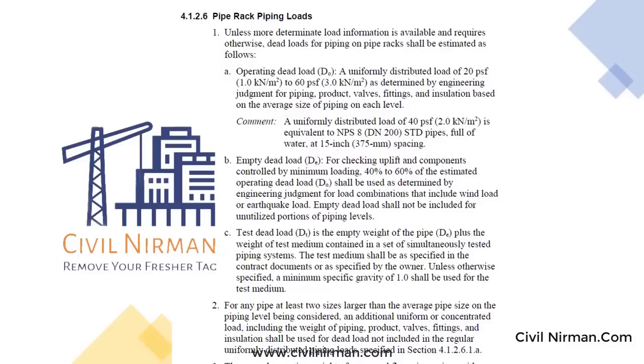Test medium shall be specified in the contract document. When such data is not available, water-filled pipe weight is considered for the test load. Hence, for big bore pipelines, concentrated force is applied in analysis software like STAAD Pro at the piping support location, while for small bore lines, UDL load is applied for the part where small bore pipelines are laid in the pipe rack.